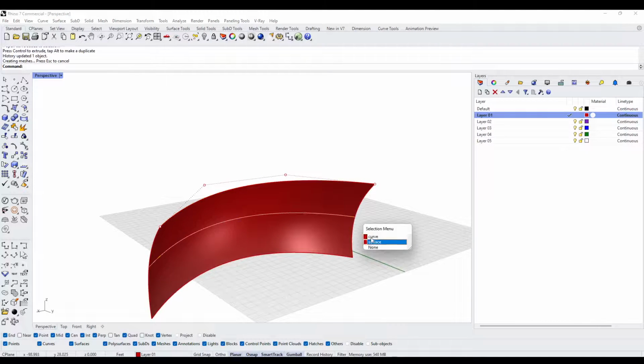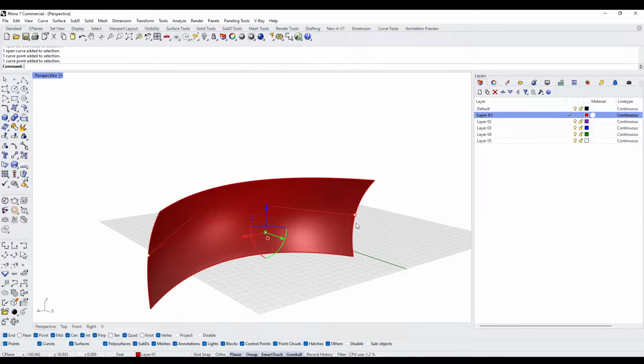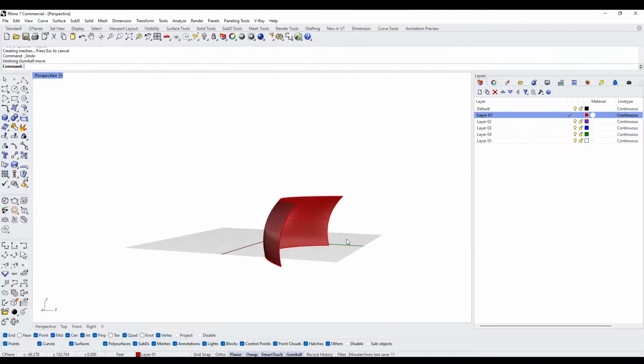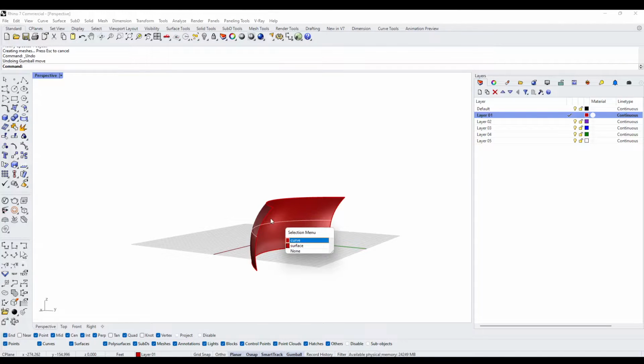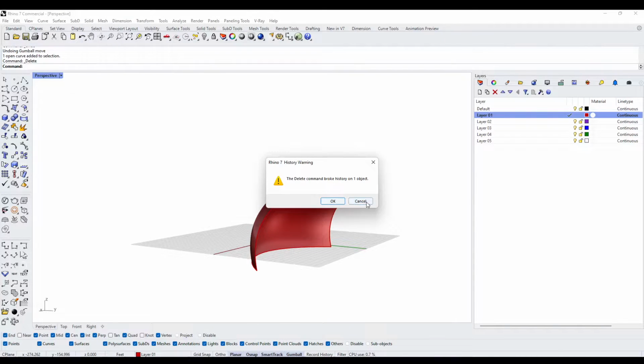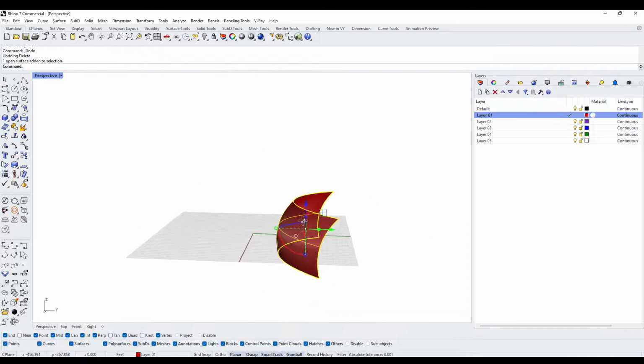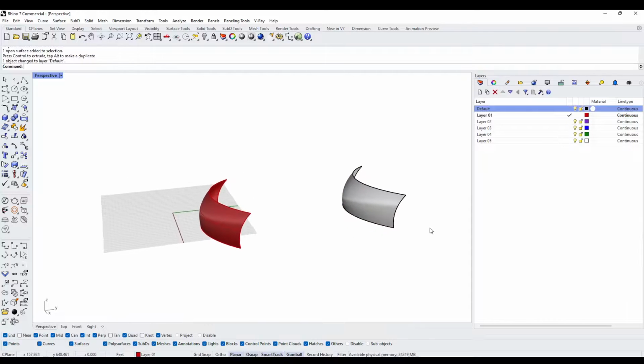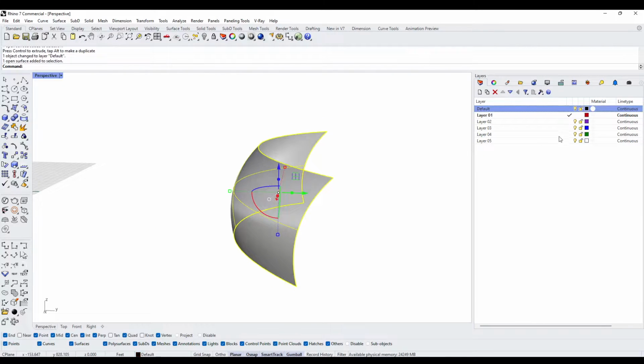And the way to get this, we can further change that surface by playing around or moving and updating those curves. The next step is going to be, so if you delete one of those curves, it will undo the history. So what I'll do is I'll take that surface, hold down Alt, move this to the side, then change object layer to this. And now we can develop this.